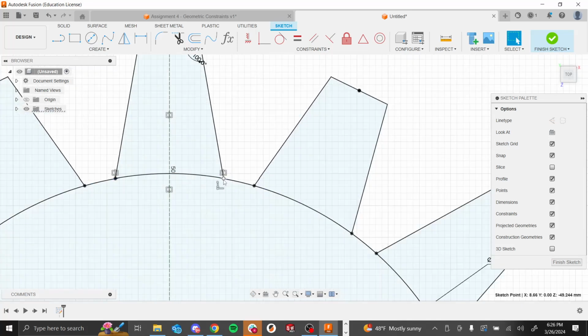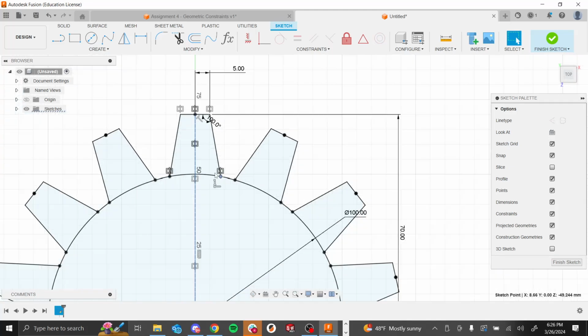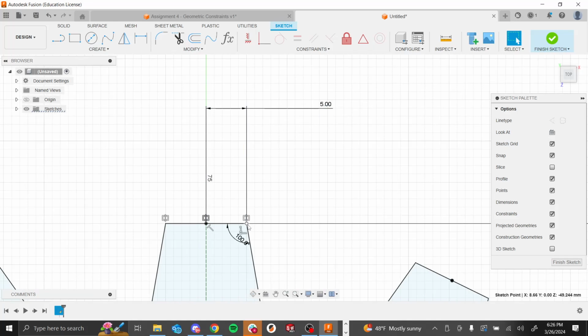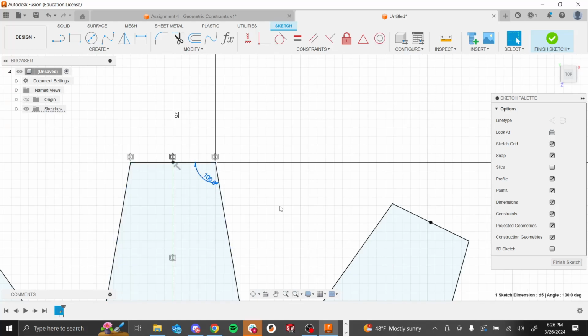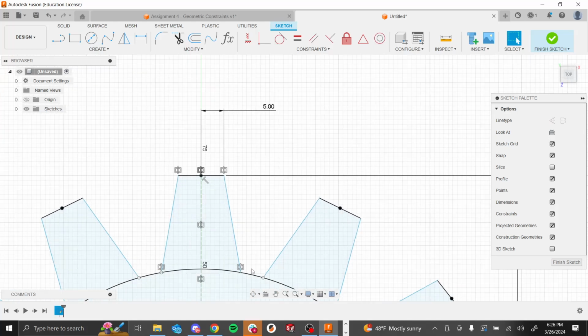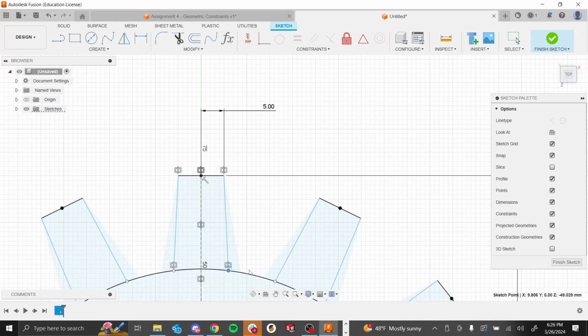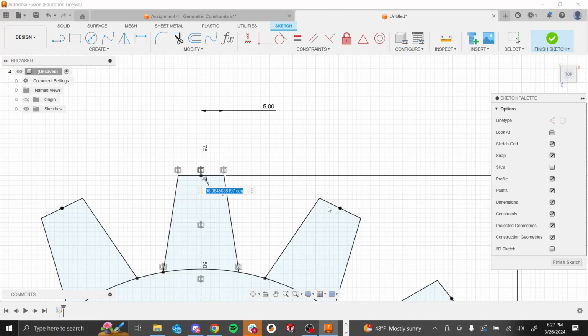Yeah, so you can see how the line ends here. Because it can't get any longer on this side and it can't go past this because it's also coincident with this line, once you set the angle, then the length of this line is going to be fixed, right? If I deleted this constraint, it'll turn blue because I can move along here and the angle will change along with the length of the line. But once I add back the dimension, then it'll be fully constrained.